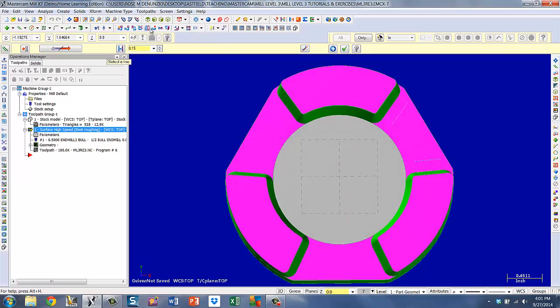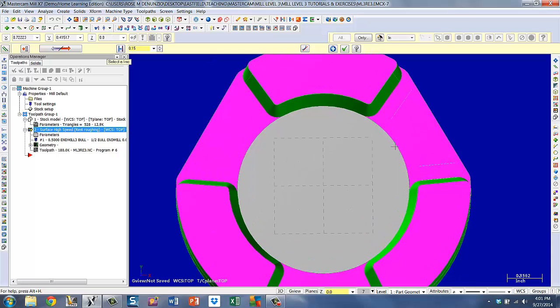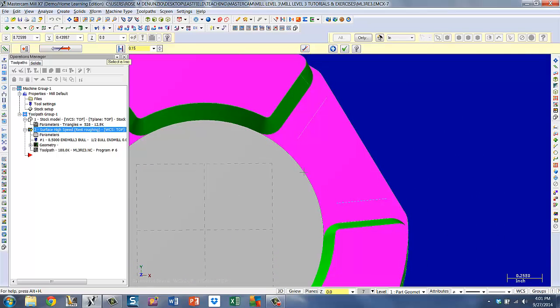Now we are asked to trim and extend the lines out. I'm going to wheel this up a little bit, bring it in, hit my scissors, select entity to trim and extend. I'm just going to pick the trim one entity at a time. You hover over this, it lights up. Select it, trim it to that line.